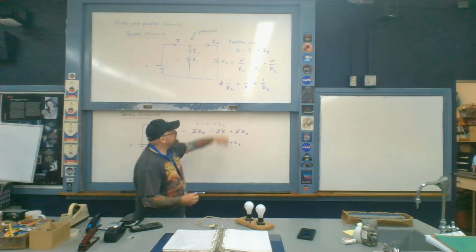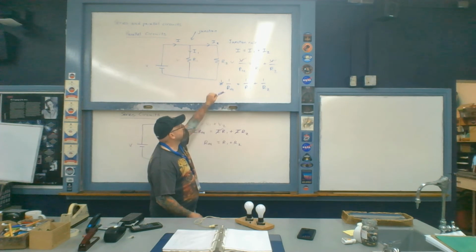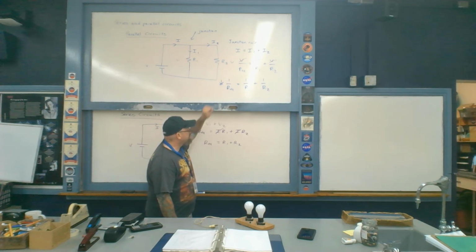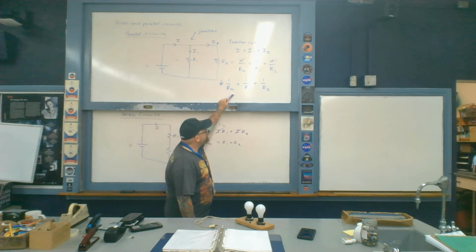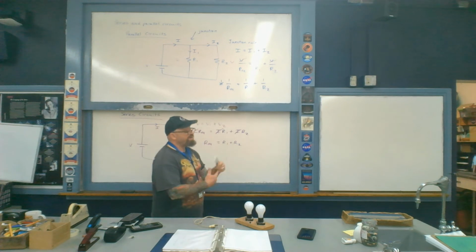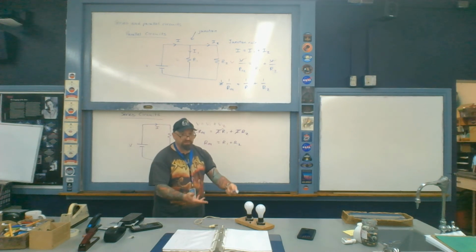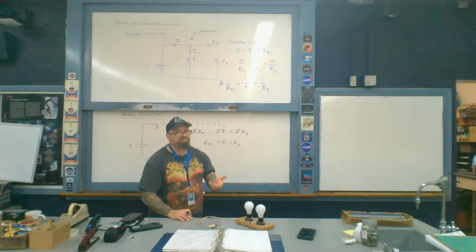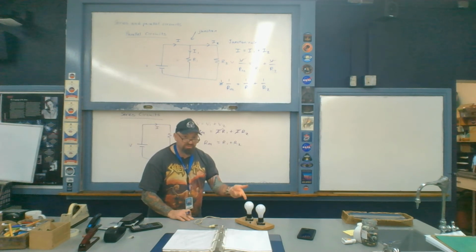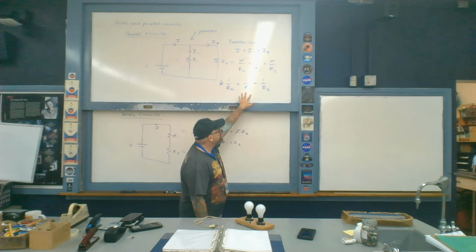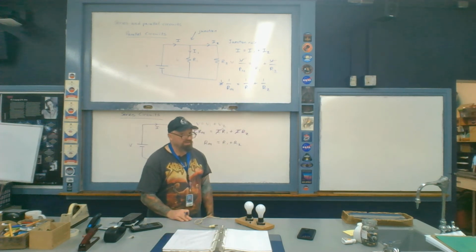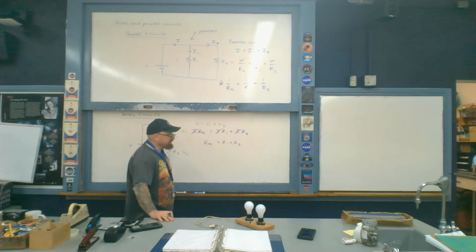Okay, now compare the two expressions to each other here for equivalent resistance for, first of all, parallel, and then secondly, for series. With respect to the top expression, the more branches that you have to the circuit, the more paths that you have for the current to flow. So then therefore the resistance goes down when you do. So the equivalent resistance, if we were to calculate it, is going to be less than the resistances R1 and R2 added together, for example.